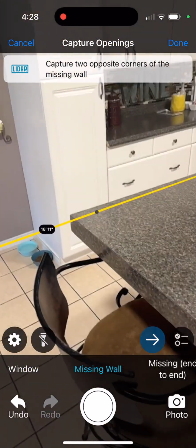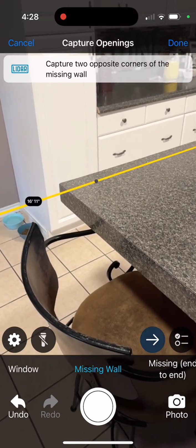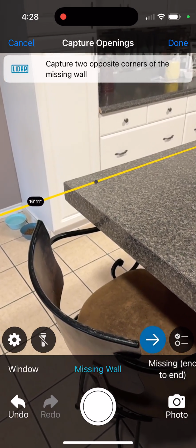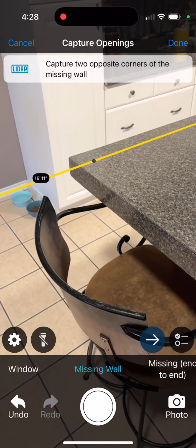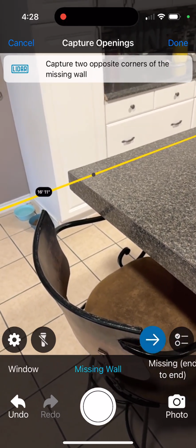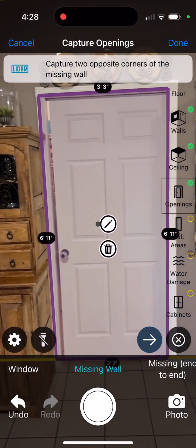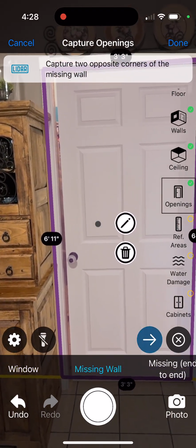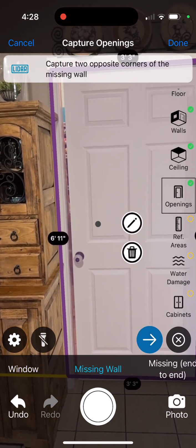Okay. To get to the cabinetry area, while we're still in the same room, we want to click this little icon to the right of the flashing blue arrow. It's got the two small little circles with a check in one and the two horizontal lines. Very bottom right corner, let's click that and we're gonna get a menu up. Let me get a background better so you can read this. Got several options we can do here. We wanna do cabinets at the bottom, so we're gonna select that icon.